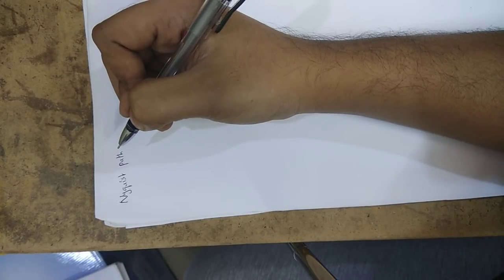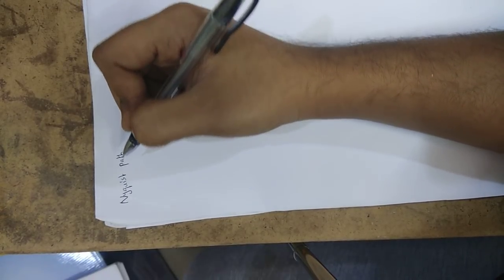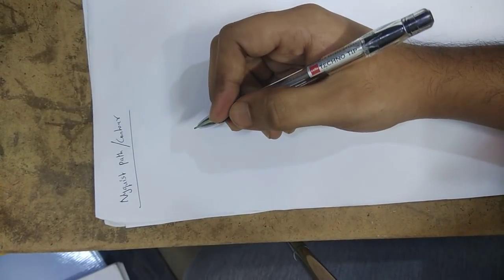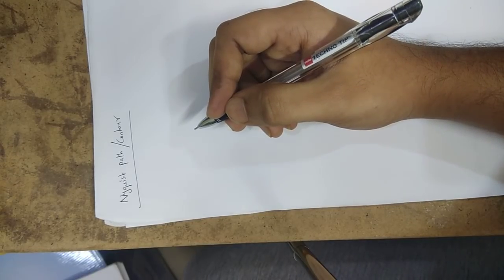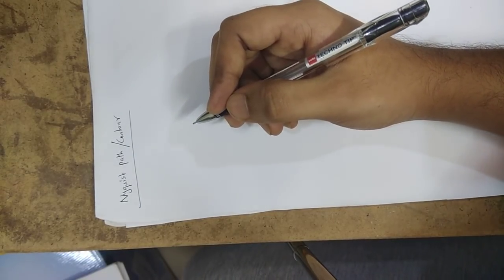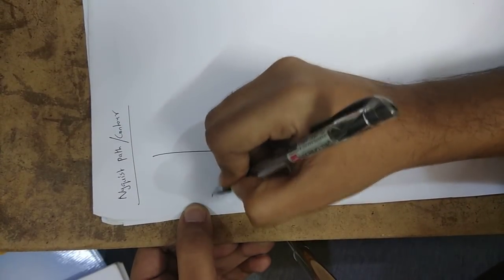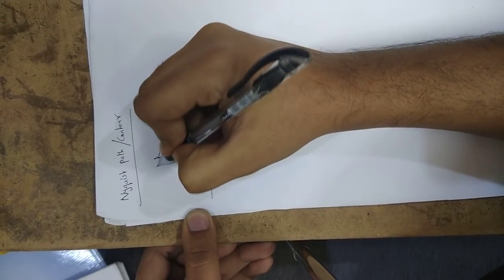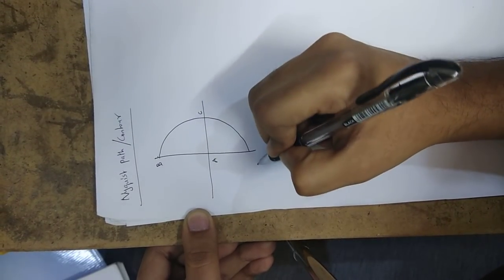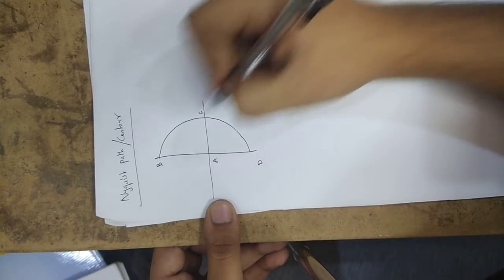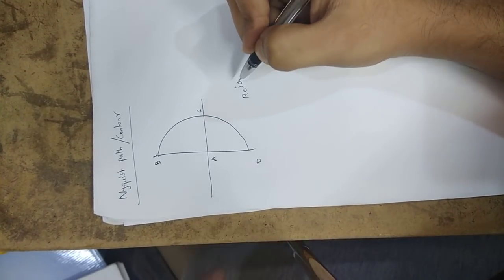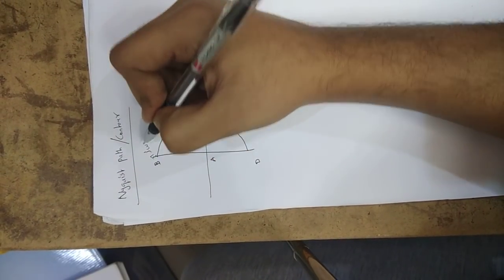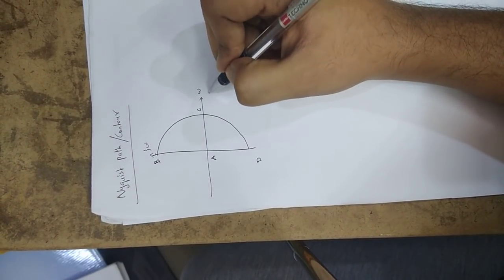Seeing the Nyquist path, we will draw Nyquist plot. This Nyquist path is also called as Nyquist contour. So there's a basic or predetermined Nyquist path, Nyquist contour is this thing. Let us consider this point A, B, C, D. This is in the form of r e power j theta, like we are representing in the form of polar form. So this is imaginary axis plane, this is the real axis sigma.